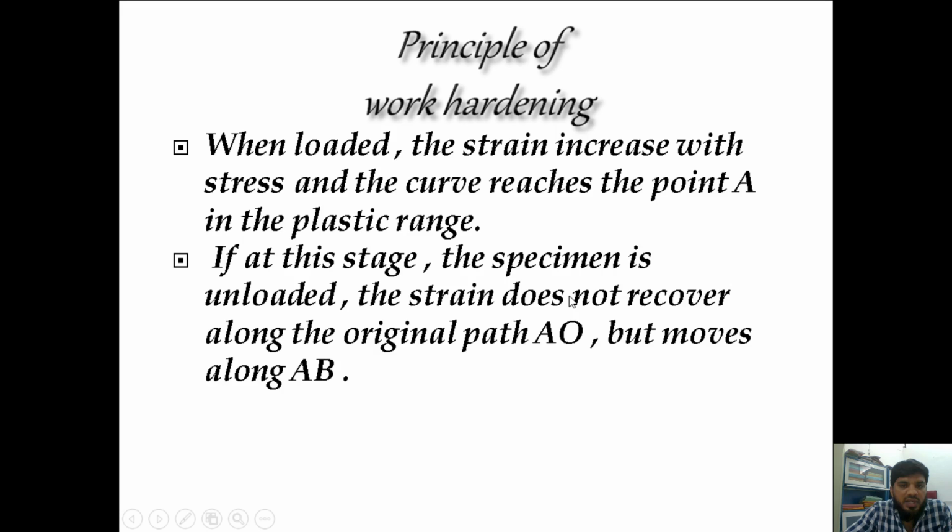If the specimen is reloaded immediately, once it comes down I am going to apply the load again. The curve rises again from B toward A, but via another path, and reaches the point C, after which it follows the curvature if loading is continuous. If you are still applying the load continuously, it will follow the other path and go to the maximum written here. If the specimen had not been unloaded after point A, meaning we had not removed that stress, then the stress-strain curve would have followed the dotted path AD dash. Okay, A D dash.